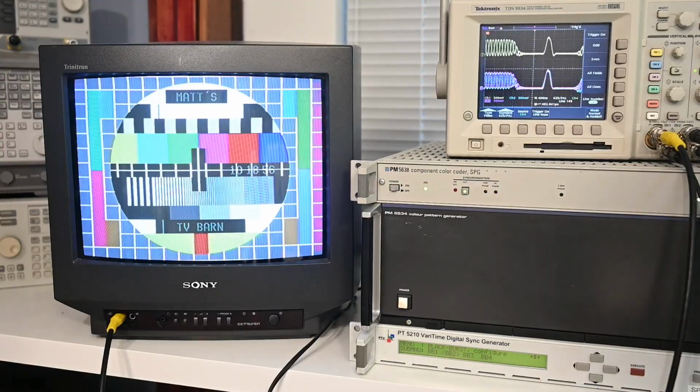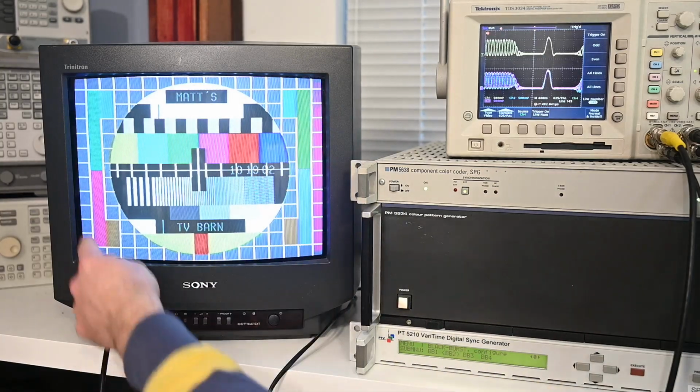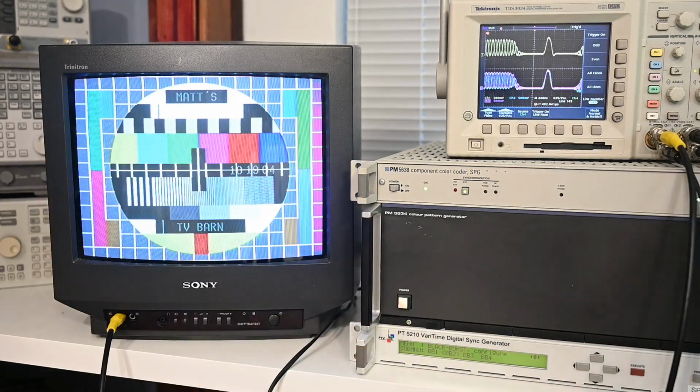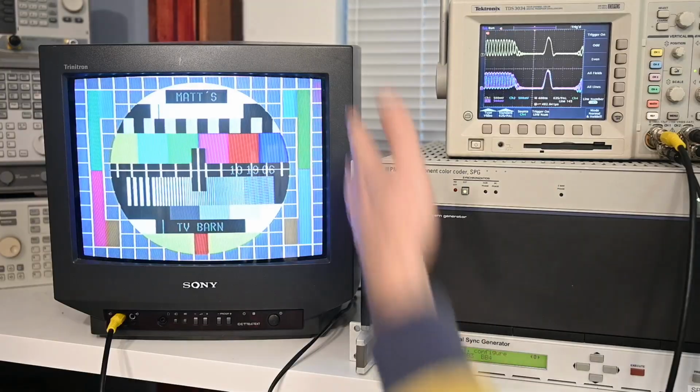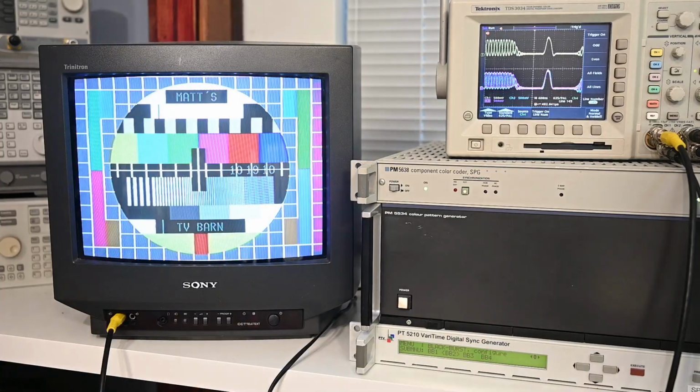Alright, so next up we have to sort out our color subcarrier phase, and if we look at the screen here, we can see this flashing, and this is instantly indicating to us that we're not in phase. The flashing areas are the achromatic fields on the Philips pattern. This is a deliberate phase error which is introduced for testing PAL decoders. And it does actually happen to be a pretty good way of seeing whether or not you've got a phase error when you're trying to mix two signals.